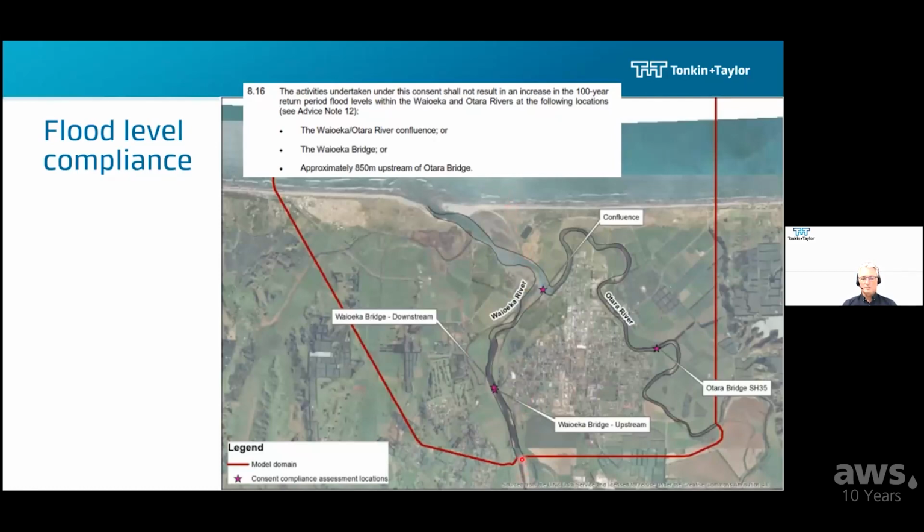The model has upstream boundary inflows from both of the rivers, as well as tidal level conditions, or sea level conditions, downstream. There was an interesting joint probability exercise we considered, where you might not get a 1% event in both rivers or in the sea at the same time. I'm not going to delve into that. I'm focusing more in this presentation on the morphological modeling.